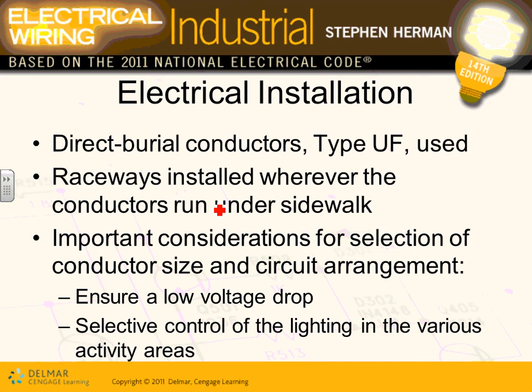You have two options. Either you have a UF cable, directly buried cable, or you can have wires and conduits. But every time you go under a sidewalk or under a parking lot, especially sidewalks, you need to go with a conduit for ease of installation and maintenance. So you have UF cable or you can use conduits, but if you use a cable, every time you go under sidewalks, guys, we typically drop a conduit there.